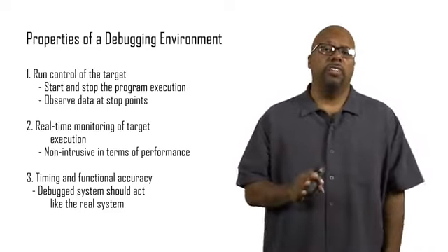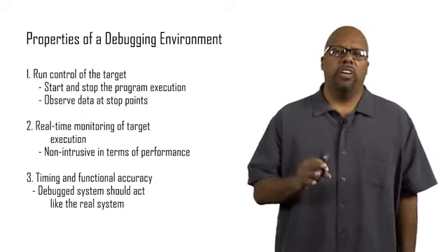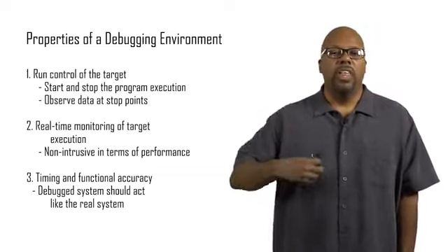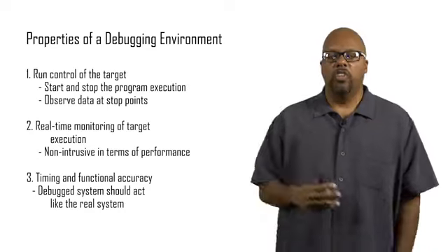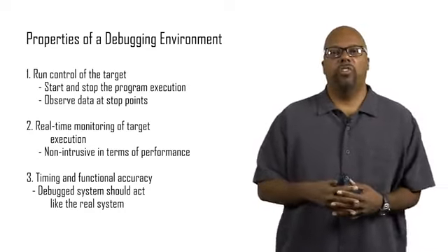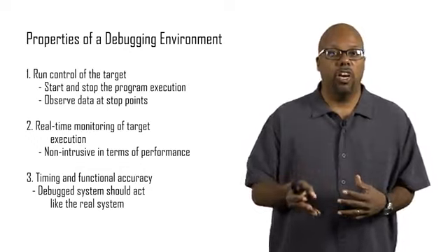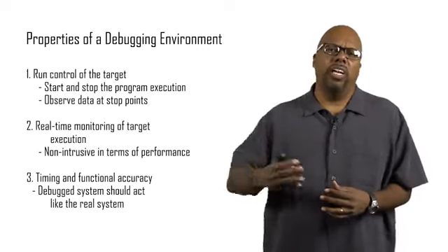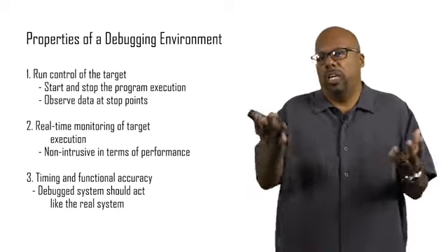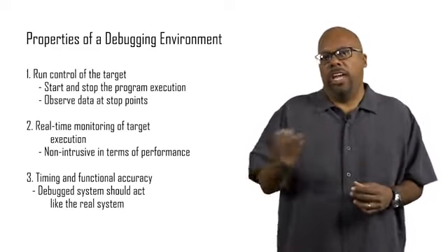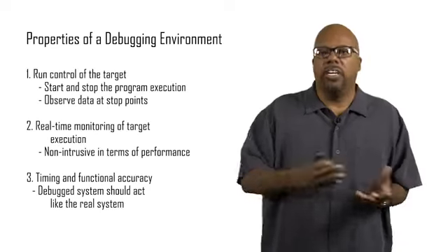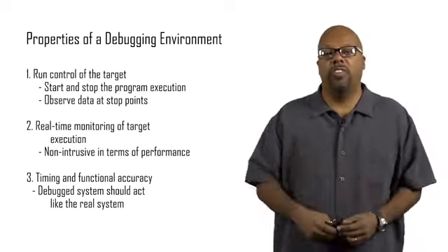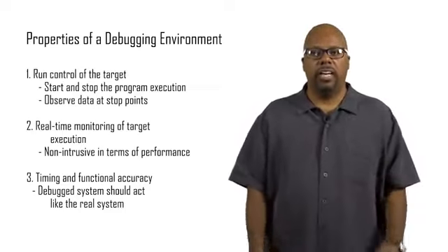Another thing about simulators is that they model most things, but there are certain things they can't accurately model. For instance, simulating an analog-to-digital converter is very hard, so sometimes simulators won't do that. Sometimes the results for the A-to-D conversion will be inaccurate. You might be doing an analog read, and your analog read data will be incorrect because the simulator wasn't accurate enough. So you want accuracy in terms of timing and in terms of functionality, if you can get it.